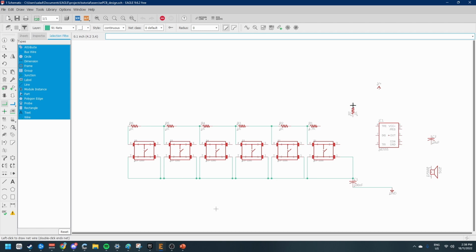You need to connect the R7 resistor to the source, and then connect this part to this 4.7K resistor R1, and then this part you need to connect to the 7. Okay, how to connect? You need to use this. This is called a net, or it can also be called a wire. So you need to connect all these wires by using this component.